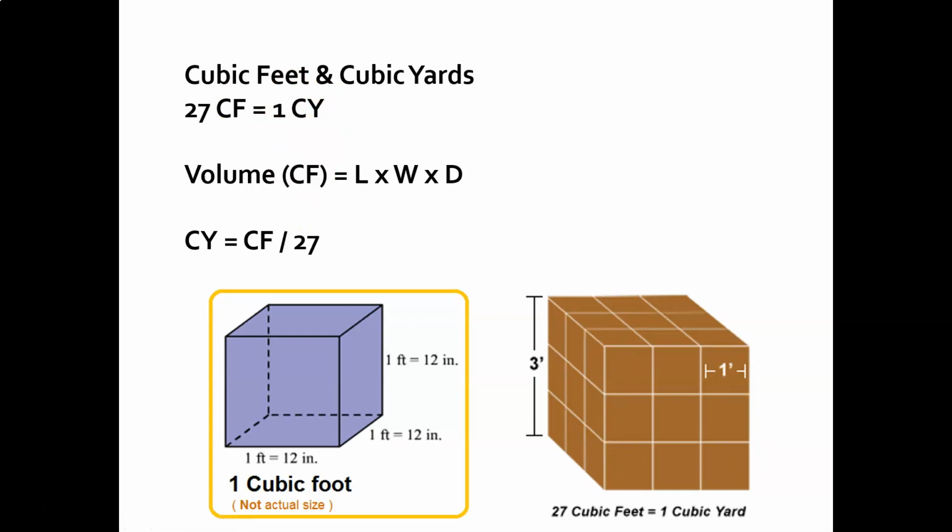All right, so when we're ordering concrete, we're going to order it by the cubic yard. So we'll calculate it in cubic feet, and then we'll divide it by 27, and that'll give us the cubic yards. So it allows us to work with smaller numbers. If we were working in cubic feet, we'd have too many big numbers, and it was just unwieldy to try to discuss. It's easier to talk about and speak with smaller numbers, basically, and write and calculate things. Gallons. So that would be paint, obviously, or tar for a driveway, for instance, come in gallons.